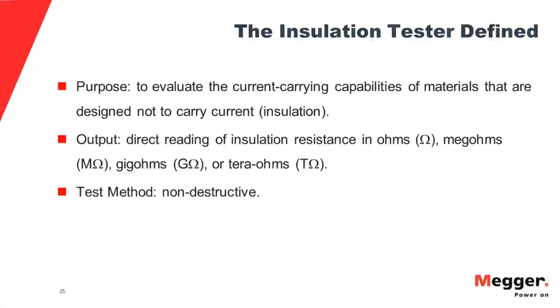That's a main differentiation from a high pot or a dielectric strength tester, which is more commonly called a high pot. High pots function in very much the same way that an insulation tester does, but they have more power. They're not concerned with measurement. They're concerned with killing the weak, taking something out of service before it can do damage in service. So always keep that distinction in your mind when you're dealing with instrumentation, an insulation tester versus a high pot.